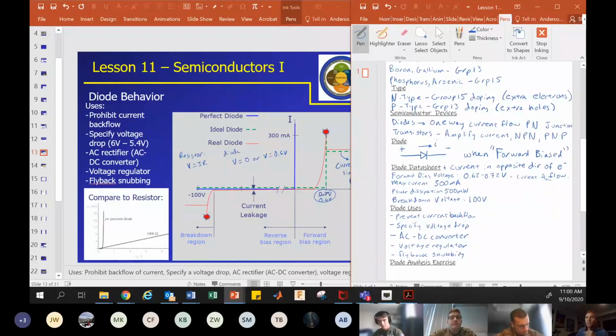DC motors are creating an alternating current, and when you turn off the motor rapidly, if the rotor is still turning, it can create a large reverse current, and a diode can be used to handle that current safely. If you don't do that, and you've got your motor hooked up to delicate electronics, like say an Arduino, it will damage those electronics. So it can be used to help us with that.